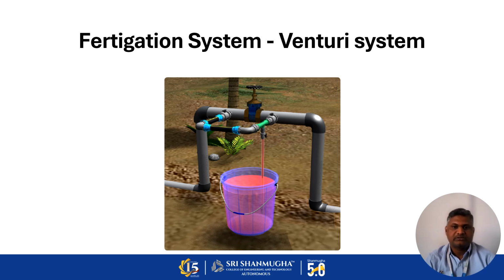The Venturi is fixed on the bypass so that a vacuum is created and the pressure drops, so that suction of the fertilizer solution takes place and it is mixed with the main pipelines.